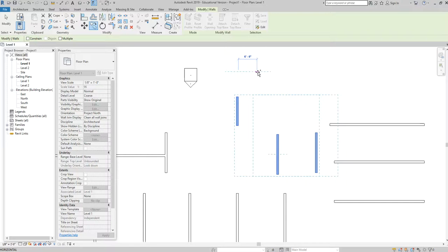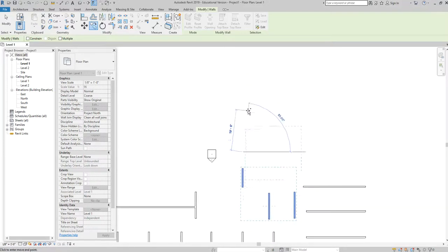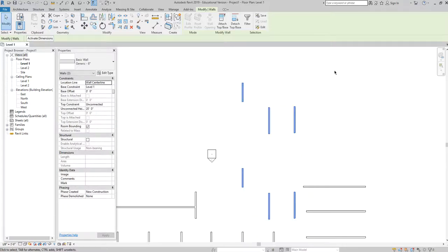As long as you just specify 16 feet, that object will be moved 16 feet. So I'm copying, and in fact, let's copy up because I don't want to go over the top of things. Let's say 40 foot 6 inches. Enter. Okay, and I just copied my objects up 40 foot 6 inches.